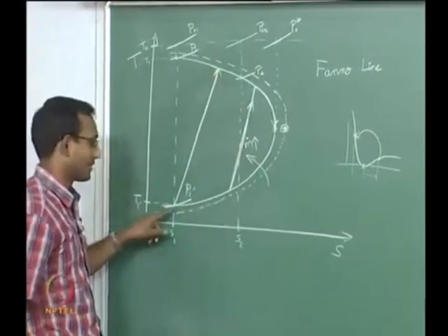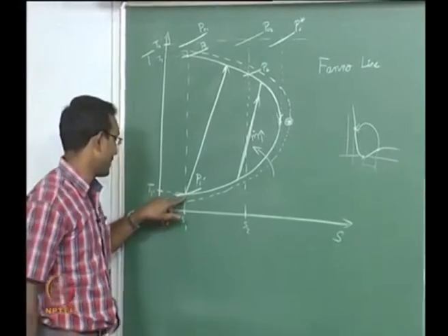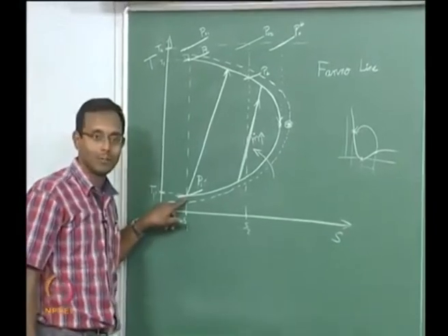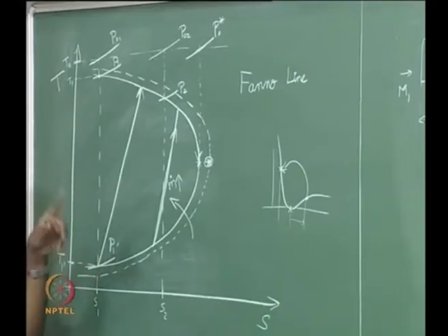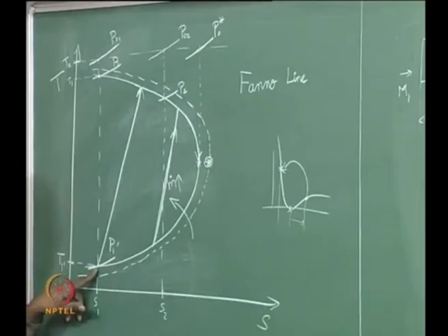This is a shock at the inlet. I said this is my inlet condition, M equal to 1, M1 prime here. This is my supersonic Mach number. If I increase my duct length any more, then the shock will jump outside the inlet. It will be in front of the inlet, where I will still have the same Mach number.